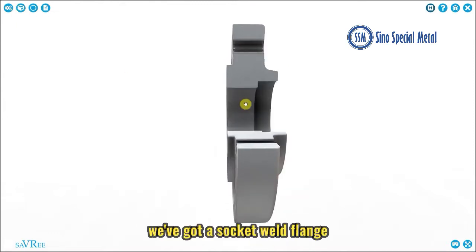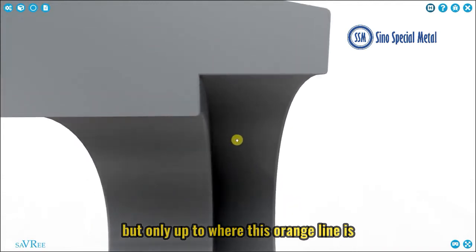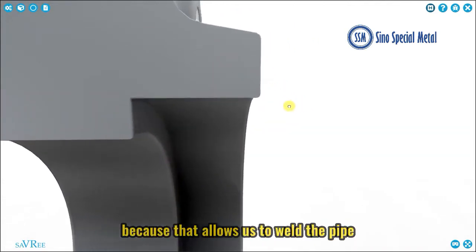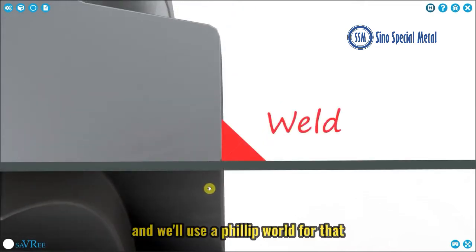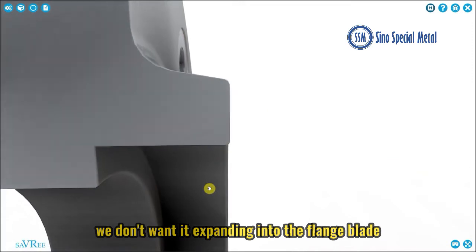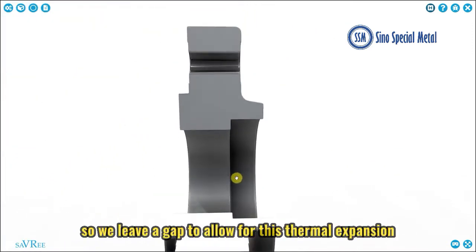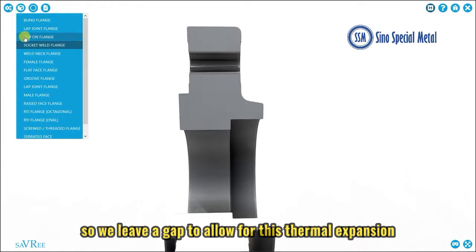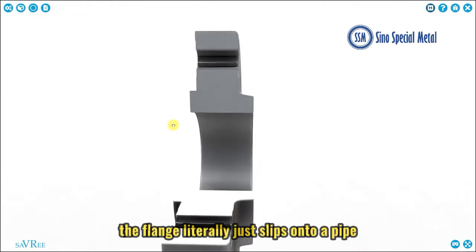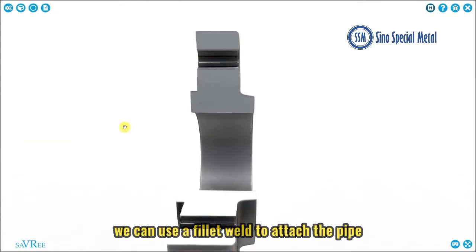We've got a socket weld flange, which you slide the pipe into, but only up to where this orange line is, because that allows us to weld the pipe, and we'll use a fillet weld for that. And because the pipe end will become hot, we don't want it expanding into the flange base, so we leave a gap to allow for this thermal expansion. We then have a slip-on flange. The flange literally just slips onto a pipe, and once again we can use a fillet weld to attach the pipe to the flange.